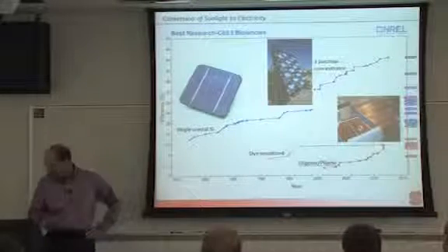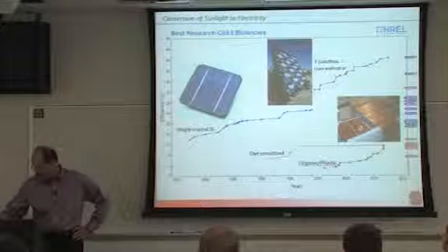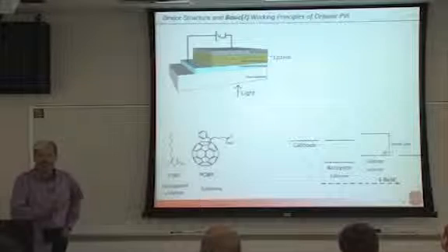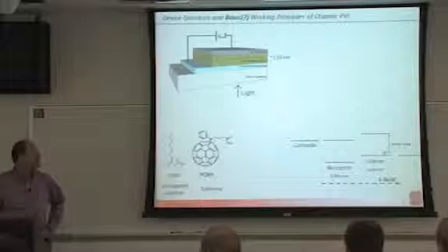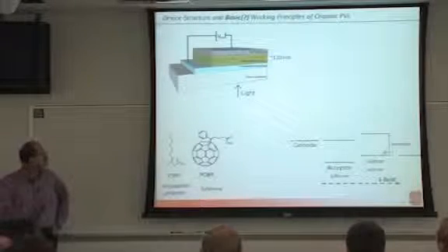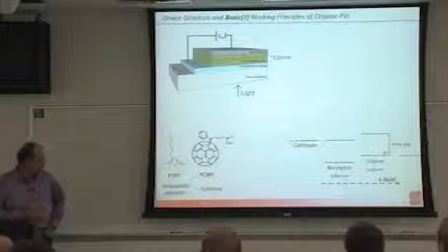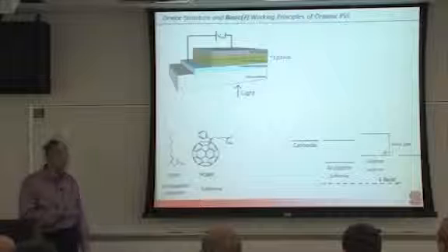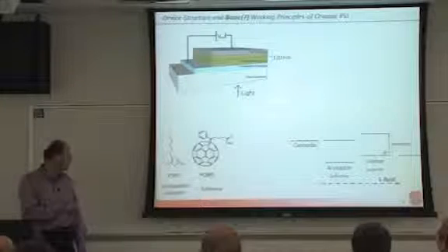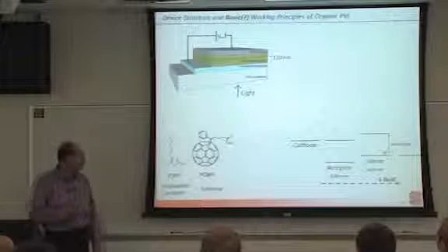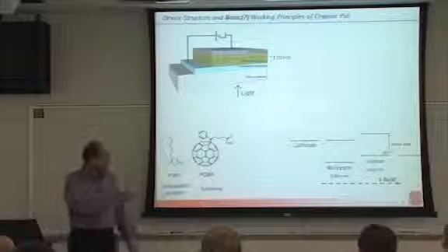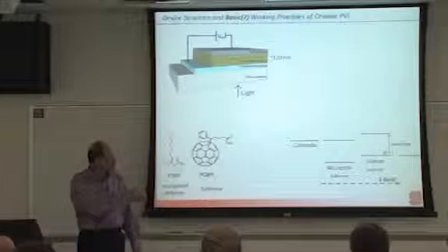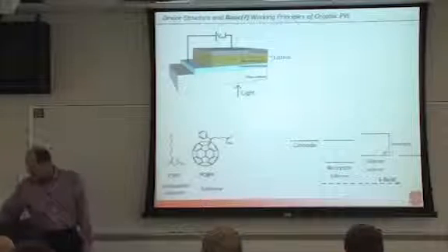So we'll look at these and try to find out what really happens. And so one needs an absorbing layer, at least 120 nanometers thick, in order to absorb a lot of light. You need some organic materials. Here are some of the prototypical fruit fly, I would say, of the field, P3HT and PCBM. They sort of have a different HOMO and LUMO. I showed that here, and so we'll go into that a little bit later.